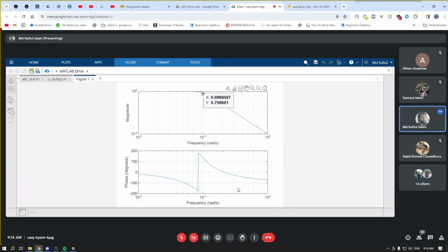So you see that this is the cutoff frequency. So where is supposed to be the cutoff frequency when my value is 70.7%, right? So let's say the y value is 0.784. That means around 70.7%, right? Or somewhere here, yeah. 0.69. That is approximately 70%. Y value is 70.7% of the maximum gain.